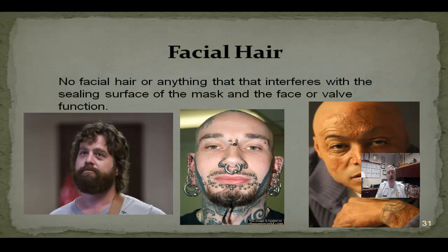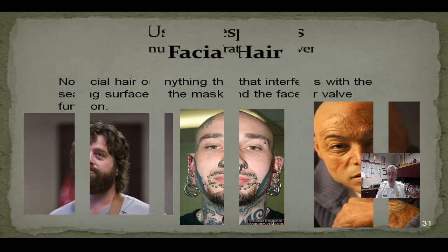Facial hair or facial modifications or burns. No facial hair or anything that interferes with the sealing surface of the mask or face or valve function. If you've got a beard, it's got to be shaved. If you've modified your face, as seen in the center picture, or if you've suffered burns that don't allow for a smooth surface of the butyl rubber of the mask to seal against your face, then you may not be able to work in these environments with a tight-fitting respirator.